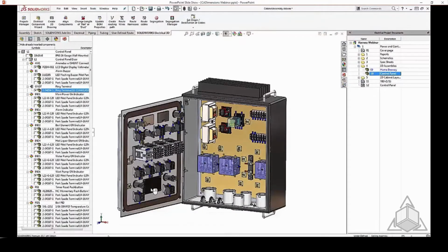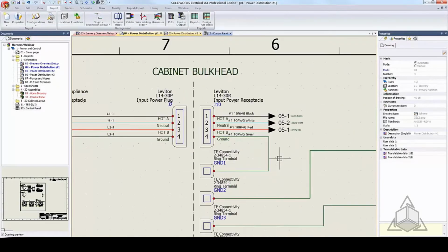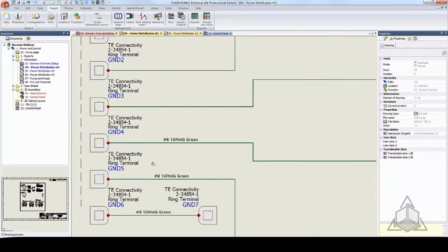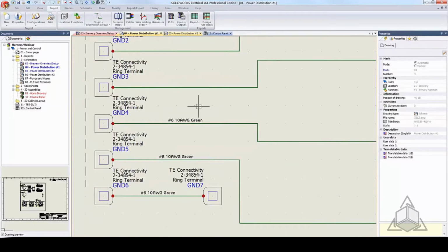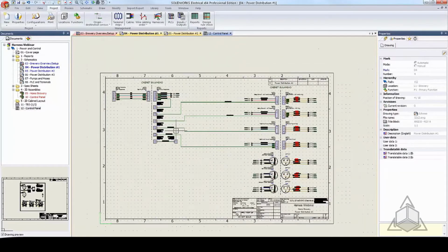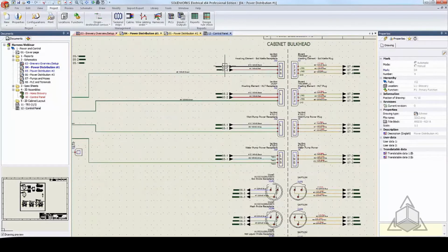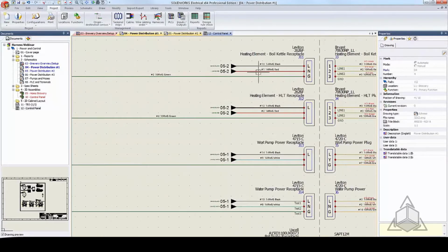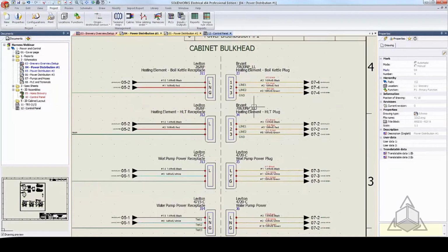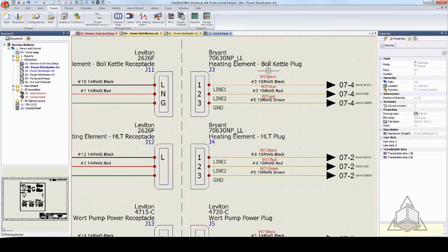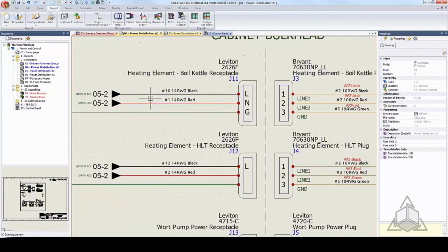All right. Actually, I'll jump into Electrical real quick here just to show some wires internal to a project. As we're dealing with different connection points, we can start to see how wires are drawn inside of a schematic. If I zoom out, we can see more of these. Most of our wires are staying internal to our panel box. We've created a numbering scheme based on the gauge and the color, as well as just a counter to make sure that every wire's number is unique. Over on our external, outside of our cabinet, we still have our wire numbering, but we also get some different coloring and different naming when we get into cable cores. We'll talk about cables in a little bit, and we'll focus on our wires right now.